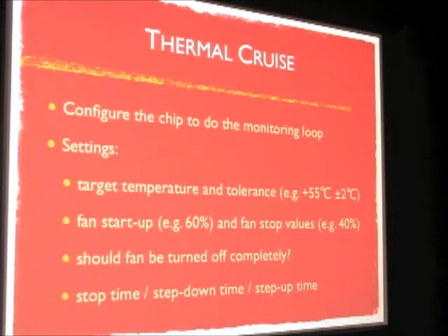And then there are also settings for fan startup speed, startup duty cycle. And generally, in order to have the fan start, you need to supply more voltage to it than to maintain the speed of the fan. So for example, in one of the previous slides, I mentioned that most fans still run at 5 volts, but some fans will not be able to start at 5 volts. So if you supply the fan with 12 volts, or with 7 volts, it will start. And then if you lower the voltage to 5 volts, then it will continue to run. But if you started at 5 volts, then it might not be able to start because 5 volts may be too low for the fan to start.